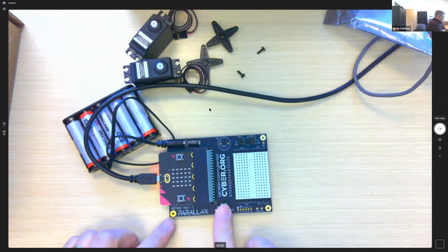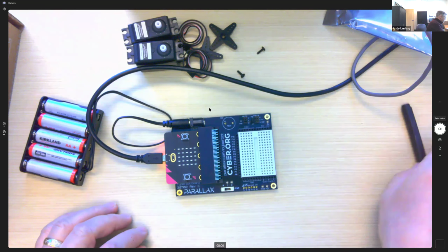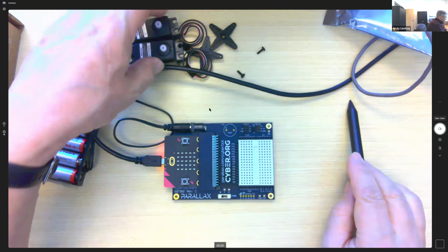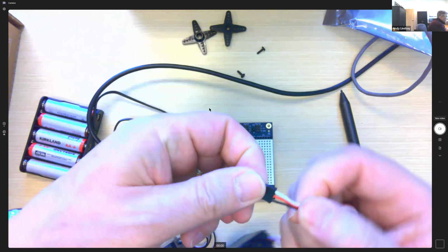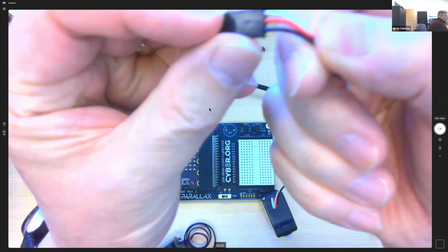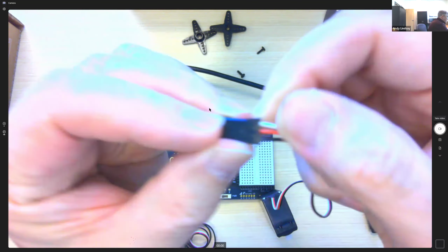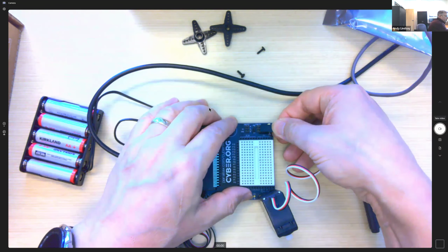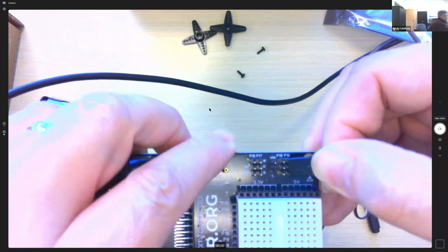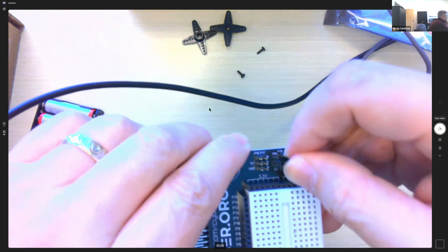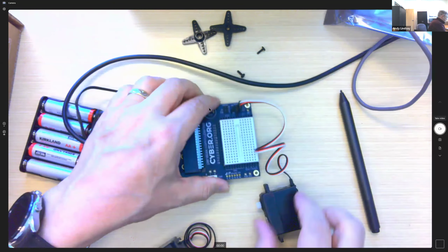Okay, so here we go. Got power turned off, set to 0 here. I'll take one of these cables and set it up so that the white wire is toward the top, then red, then black. Then I line the holes up, the 3 holes with the 3 pins, then slide it down until it won't slide any further downward. And we'll do that for both.